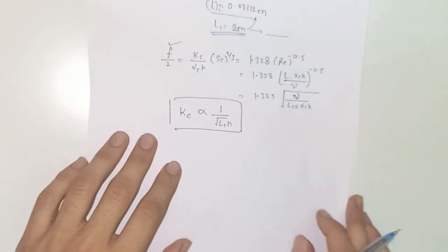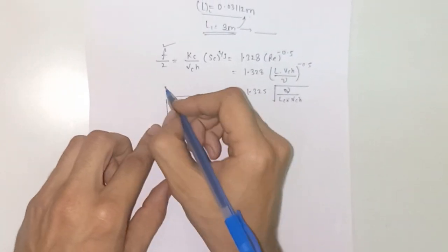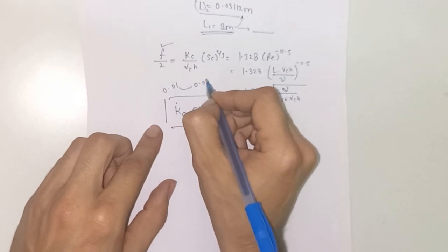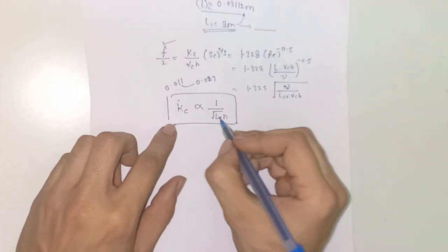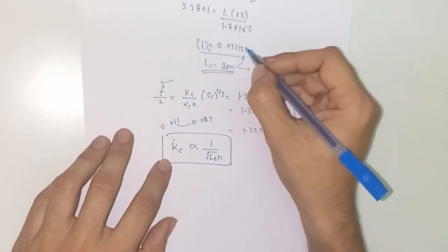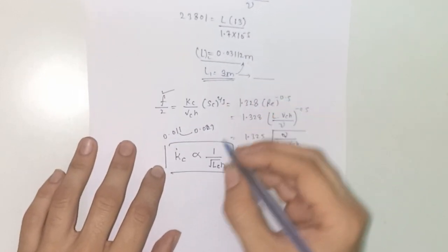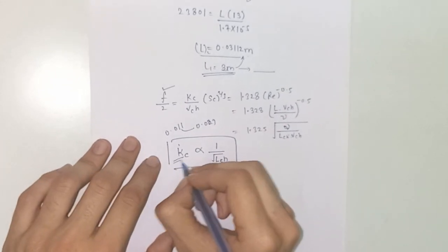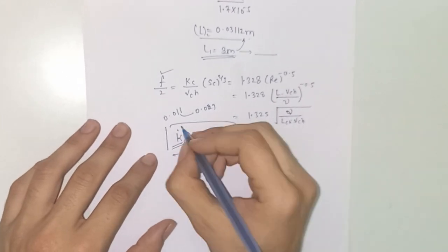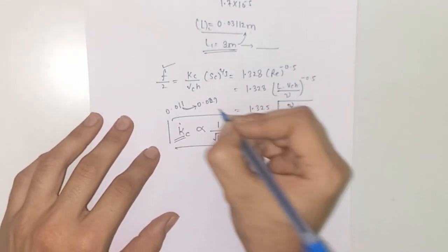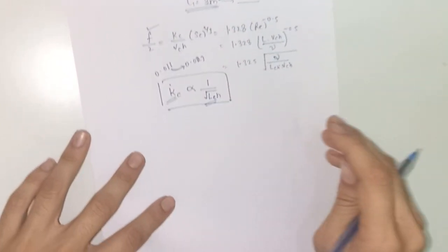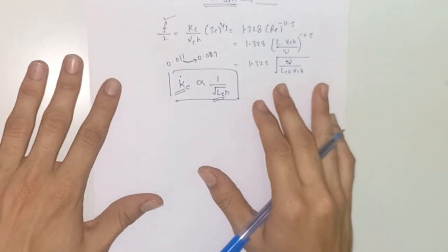So now we can see that when Kc increases from 0.01 to nearly 0.029, the value of the characteristic length L decreases drastically. This is because the characteristic length and Kc have an inverse relationship under the root. So that is why a small increase in the value of Kc gives a drastic decrease in the value of L. So this is all about the problem on transport phenomena.